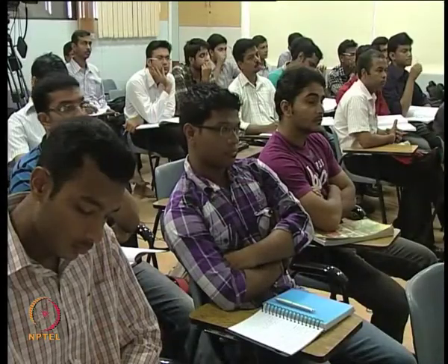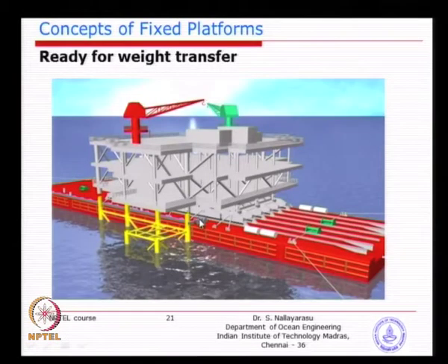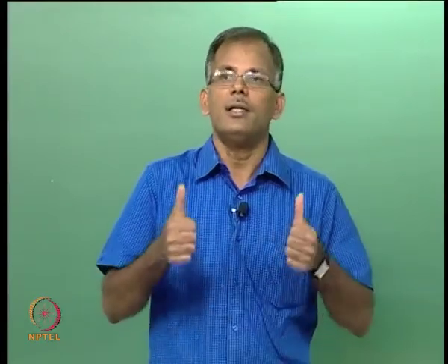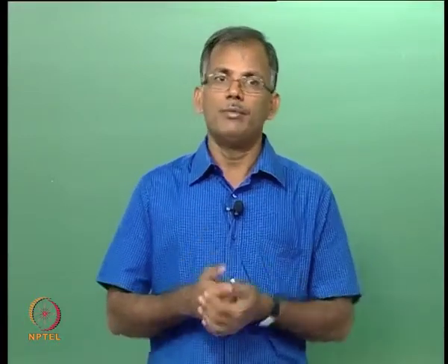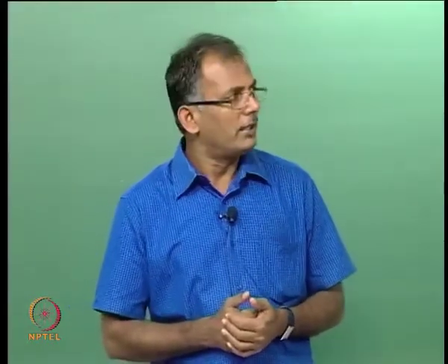So, in order to avoid that, what we normally have is, I think that slide is not here, but what you can see here, instead of supporting all of them only by simple welded supports, you can support the whole structure by hydraulic jacks. If you have say 10 or 18 hydraulic jacks below the structure, in case it is moving down too fast, the hydraulic jacks can lift the structure by half a meter, whatever is required to stabilize. Or if the movement of the deck is too slow compared to what you expected, because ballasting is going very slow or you are unable to do ballasting, then you can bring the jacks down. So, this we call active float over.